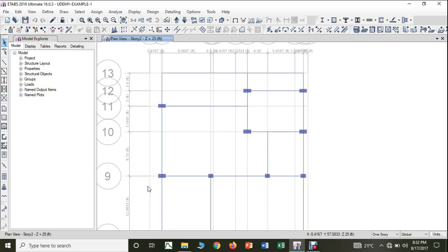So due to that reason, the orientation of the column plays a very important role. Along with that, another important reason to orient the columns properly is to avoid eccentricities. Especially in a residential building, you have to avoid orienting the columns in such a way that they come out of the wall, because it will affect the architectural or pleasant appearance inside the houses.